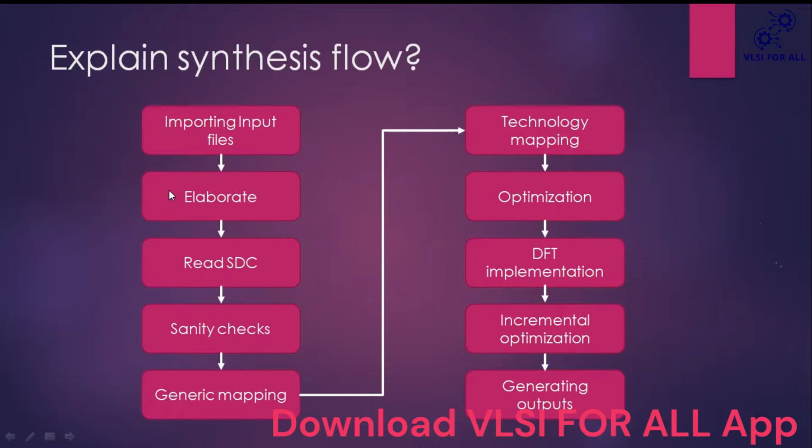So we have to specify those commands in SDC. These are timing guidelines for the design. The tool uses this SDC and follows all these timing guidelines to implement the design.